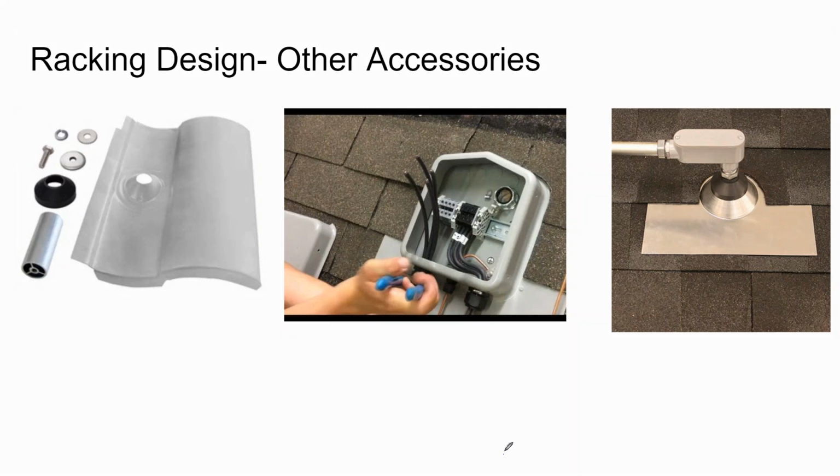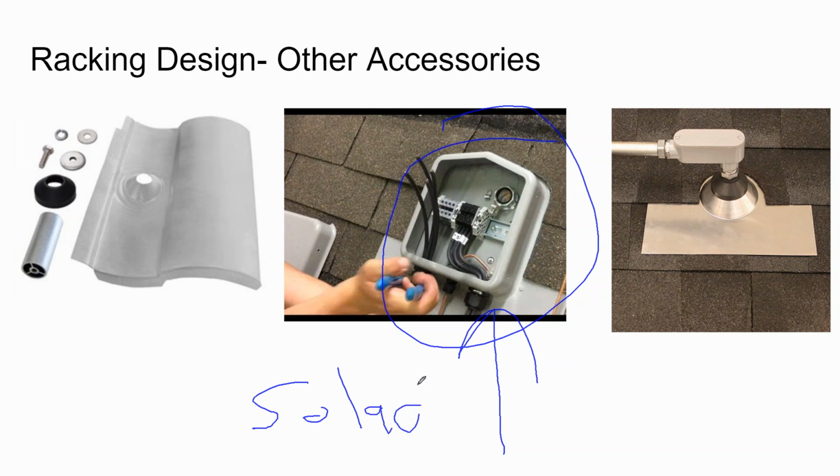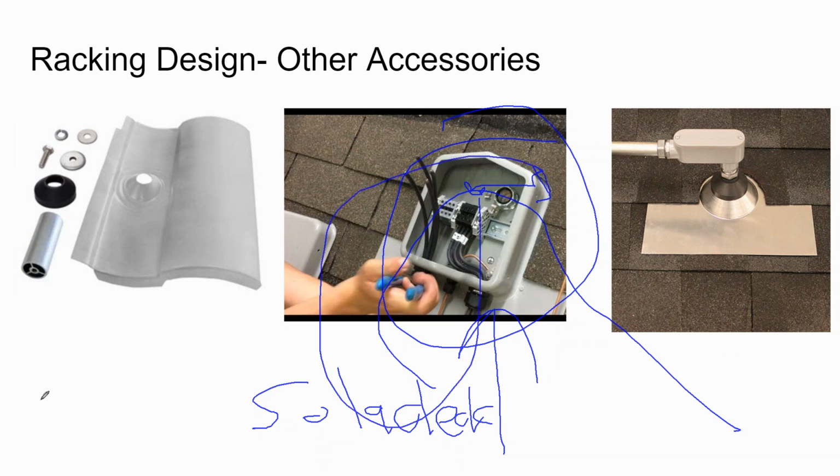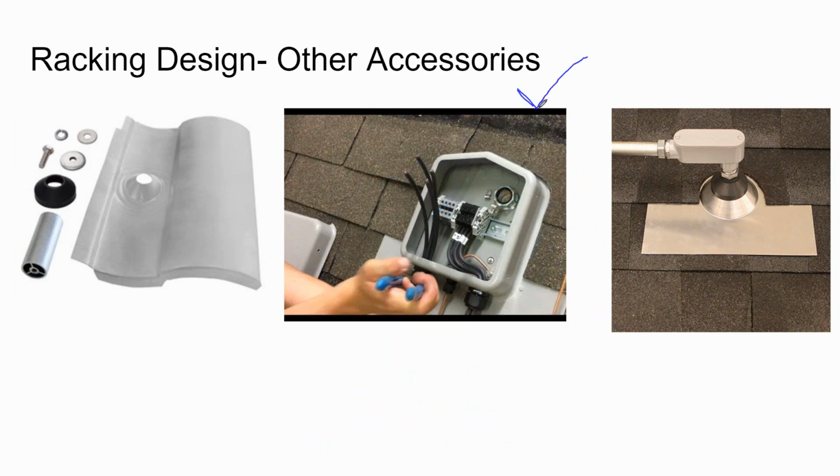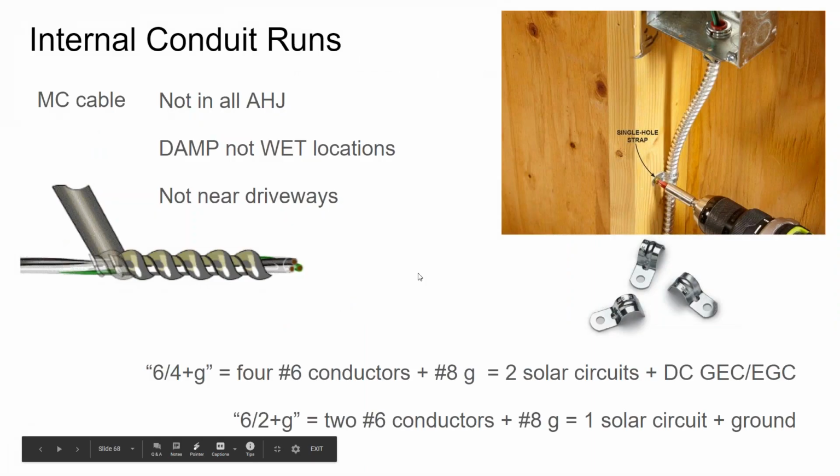Another specialty component you need to buy is a transition box for going between the attic and the rooftop. So this is called a Soladeck, and often I will just buy an empty shell Soladeck and just dump my solar cable into my MC cable and keep on going at this point. The problem is if you don't buy the specialty box, the Home Depot balance of system equipment material can stick too far up off of the roof deck to hide underneath the array. So if you want a good aesthetic, you've got to hide it underneath the array.